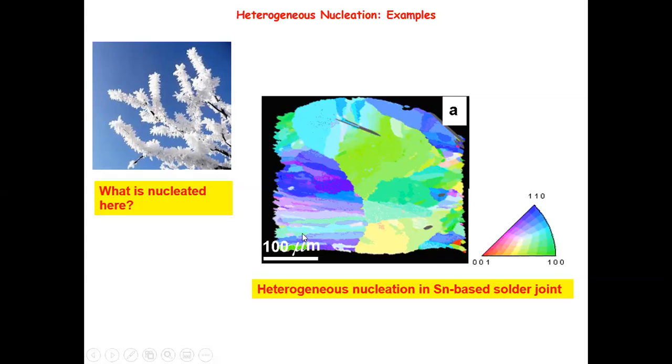So the reason why you see these grains is that this is probably the place where the melted solder first touches the copper surface, so it quickly starts to nucleate, and nucleates a lot, because on the copper surface there are always some impurities. Those impurities are very nice nucleation sites for the solid tin solder to form small grains.